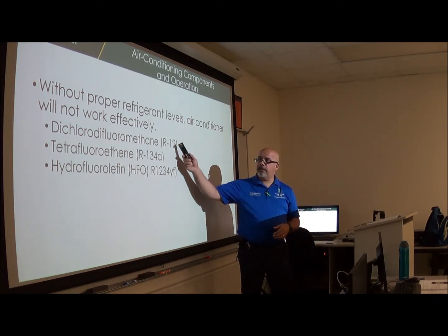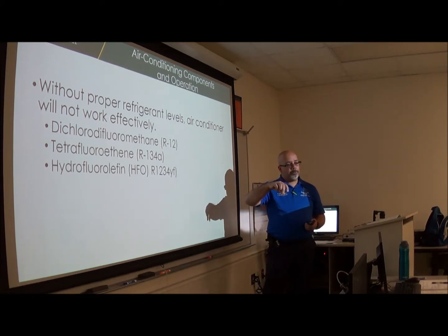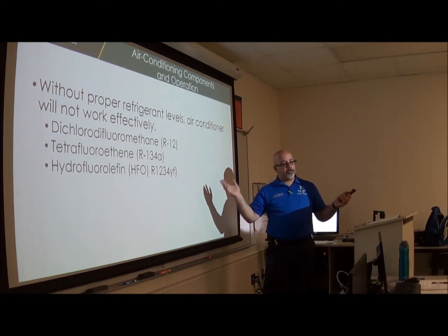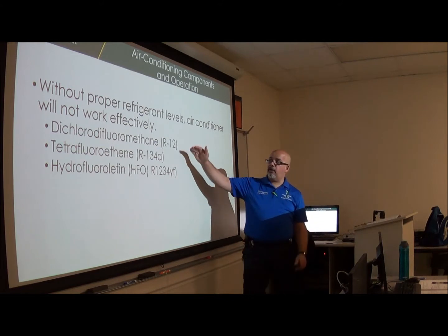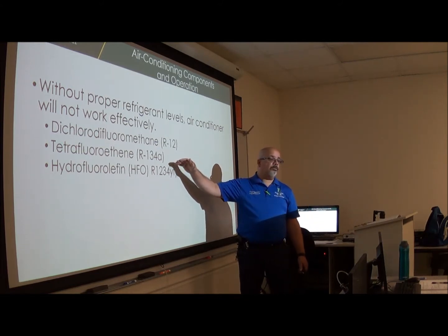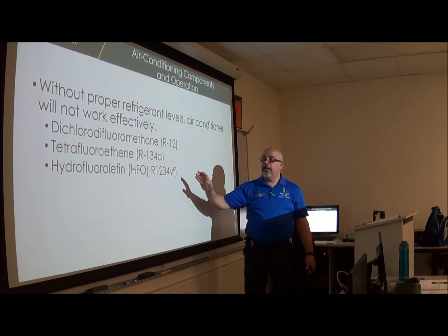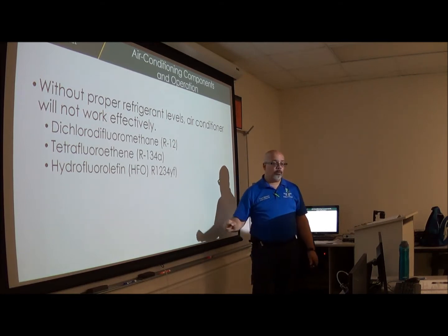Then on the fitting for R12, we would put an adapter, and then we could fill the same car that had R12 with R134. Now with 1234YF, we are not allowed to do that anymore.